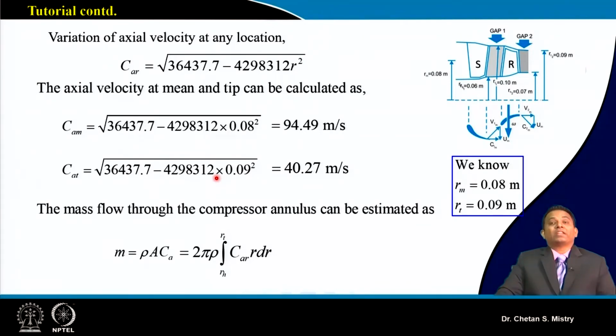You can understand it says my design configuration for this blade is of a different kind. And if you recall, the axial velocity will be varying with different configurations. Okay. So this design may be of such kind. So this is how we can do our calculation for axial velocity at the midsection and at the tip section.